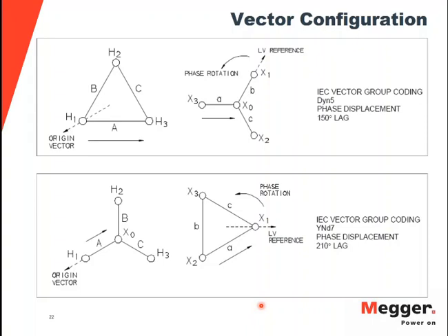Okay, let's look from the physical point of view. The first thing you have to remember is that a transformer is mainly a big inductor with a very, very small resistance. And when you apply DC for any process of saturation or demagnetization, you are playing with a time constant, which is the relation between the inductive component and the resistive component of your transformer. So you cannot split those two apart. And that means that there is a time function, right, for you to see stability on your variation of current with respect to the variation of voltage.